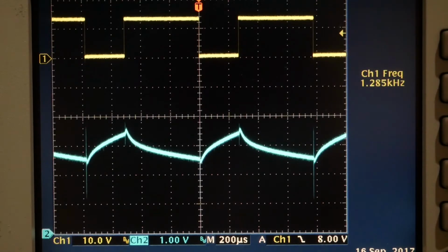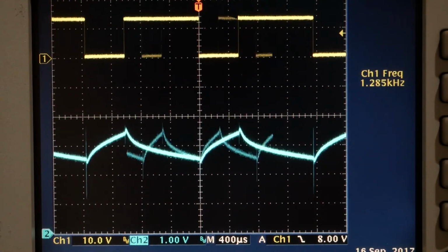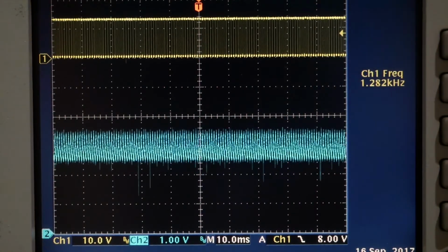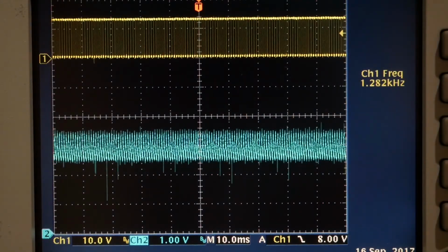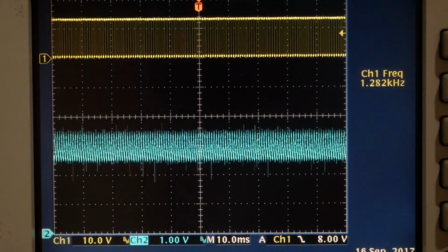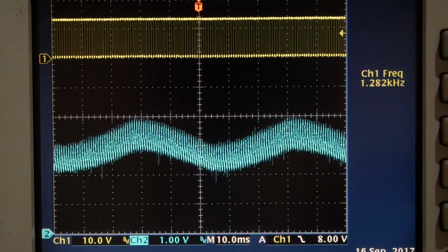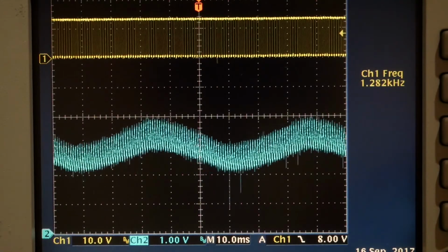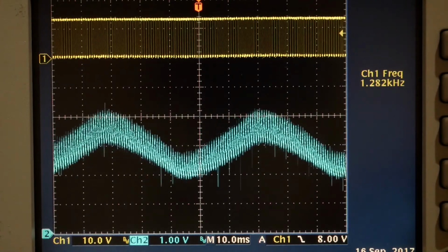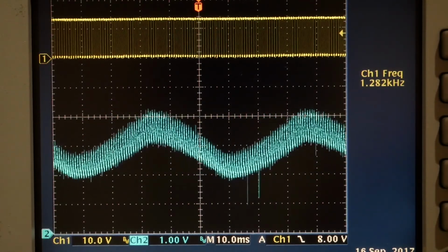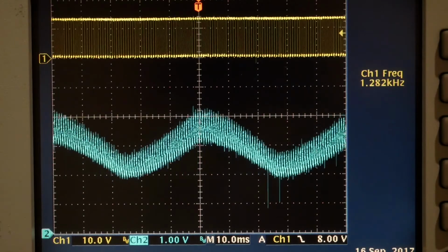Like other parameters, the frequency and amplitude of dither is controlled by commands sent from the PC to the USD-II. In order to see the effect of dither in action, I first slow down the oscilloscope sweep to view many PWM cycles because the dither frequency needs to be much lower than the PWM frequency. As I turn on dither, you can see the variation up and down of average PWM current according to the amplitude I commanded. If I increase the amplitude of commanded dither from my PC, the effect is seen immediately on the oscilloscope.